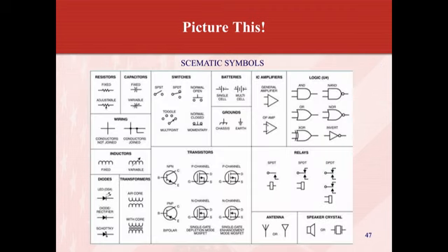Okay. And this is showing off a bunch. There's quite a lot here, a lot of different schematic symbols. They're giving you, looks like, maybe 20 or so. But the basic ones are more or less in the upper left corner. You've got your resistors. Resistors are always going to have that squiggly, sharp line on them. And then they show capacitors, which usually have the separation there. One thing they're not saying, which is a little bit of a side note, is that for a fixed capacitor, the bent side that's half circular would be the negative, and the positive would be the other side.